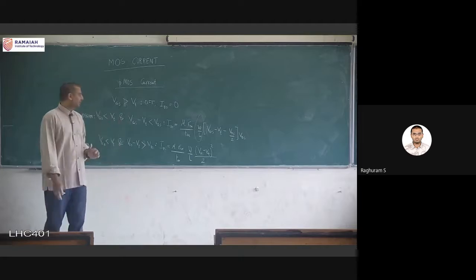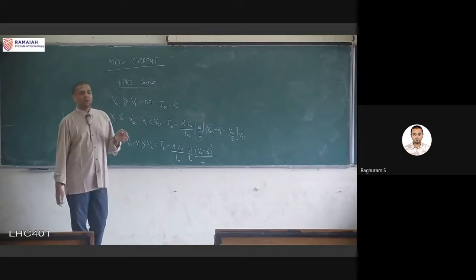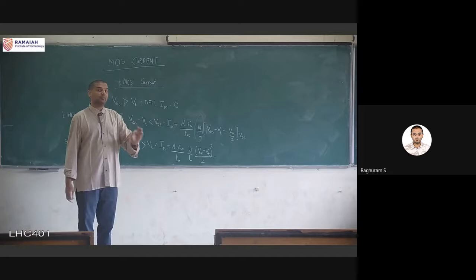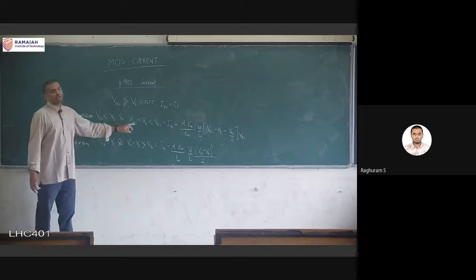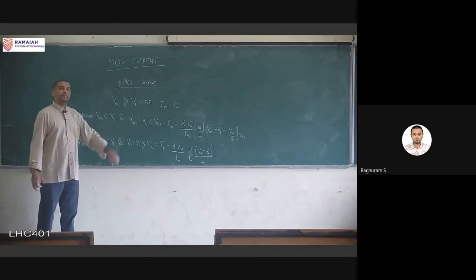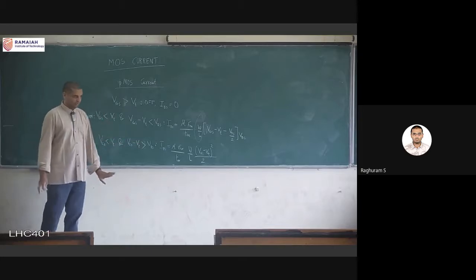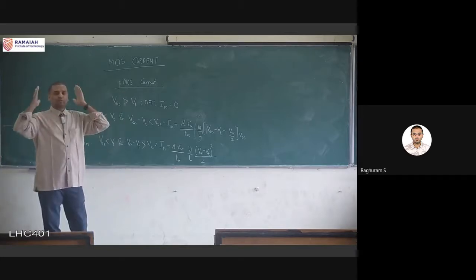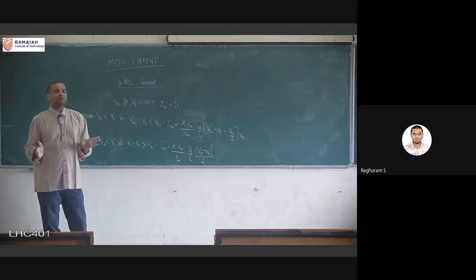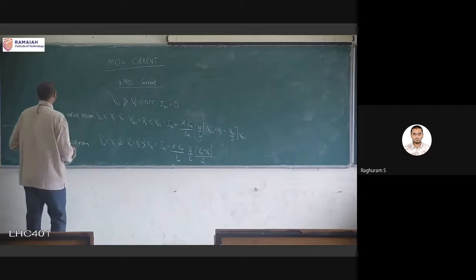So it becomes opposite. The first thing to remember is that the linear and saturation current equations are the same for NMOS and PMOS. The only difference is in the voltage conditions for linear and saturation. The NMOS linear condition becomes the PMOS saturation condition, and the NMOS saturation condition becomes the PMOS linear condition. So the best thing is to remember the conditions accurately for the NMOS transistor. If the numerical has a PMOS transistor, you just invert the conditions. That is the best way to remember both sets of conditions together.